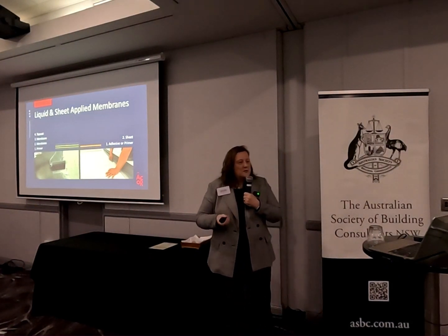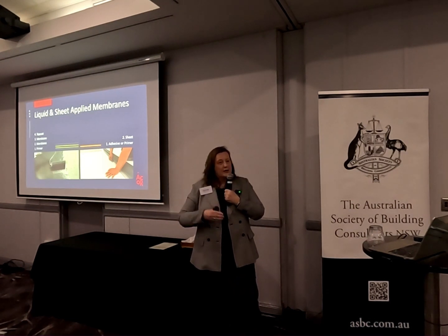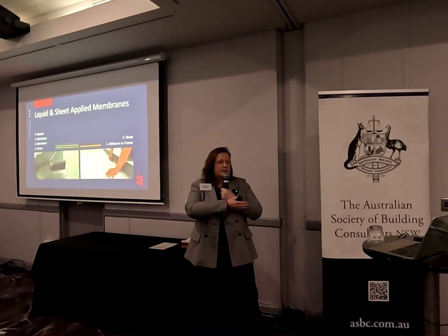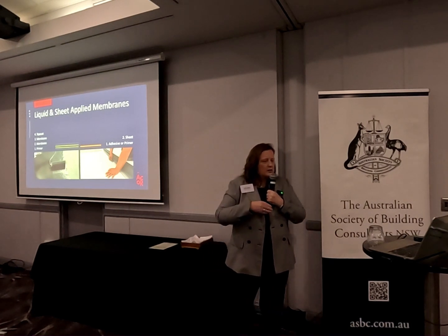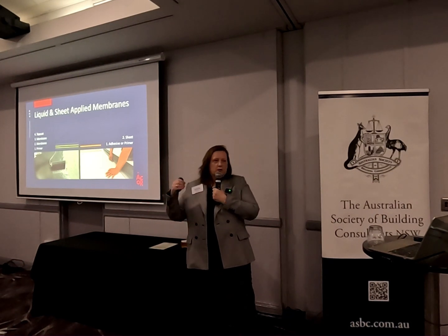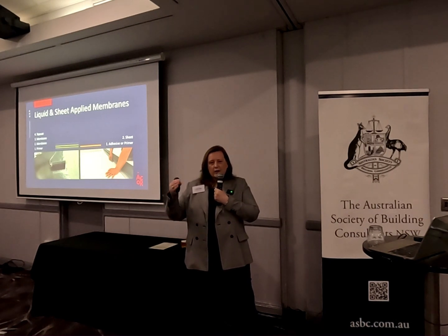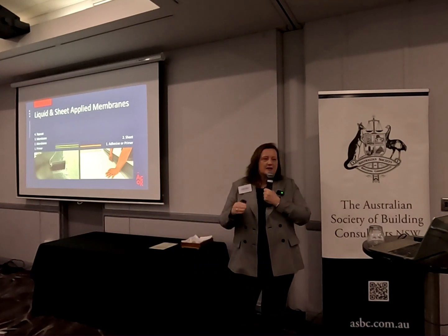I don't want to spend a lot of time on this slide because this is the old debate, liquid versus sheet. I wrote liquid and sheet, because the fact is there are some products that are more suited for some applications than others. In fact, there was a LinkedIn post this week. I saw a remedial consultant proudly saying, on an exposed balcony, we would never use liquid membranes. We would only use sheet because we use the best. But the reality is there's no sheet that's going to be suitable for exposed traffic that any manufacturer, I think, would stand by. And in that case, that's probably one of the ones where you must use a liquid membrane.